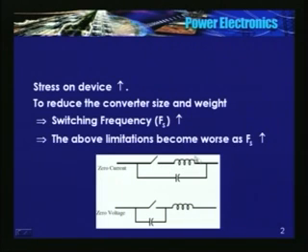Because of this inductor, current through the switch cannot change instantaneously. It has to start from 0 and slowly rises, slowly increases because of this inductor. Hence the name zero current switched converter. I will repeat. I will close the switch; at t equal to 0 minus, just prior to closing the switch, it is 0. I close it, still the current is 0 because of this inductor, and now current starts increasing slowly.